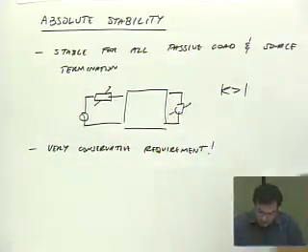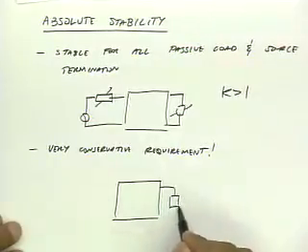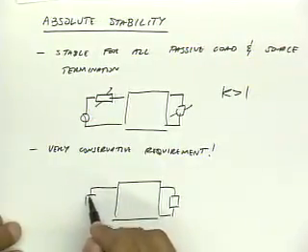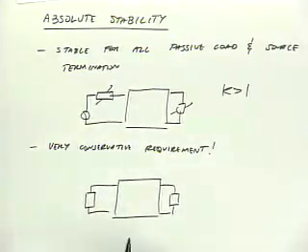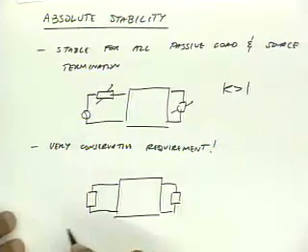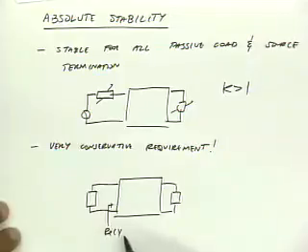Well, what's also interesting is if I have something that's not stable. So let's say I have a 2-port that's unstable, and I want to stabilize it. What's a really easy way to stabilize this 2-port so that I make it unconditionally stable? Exactly. Add positive conductance. Remember, instability means that if I look into here, the real part of y in is less than 0.